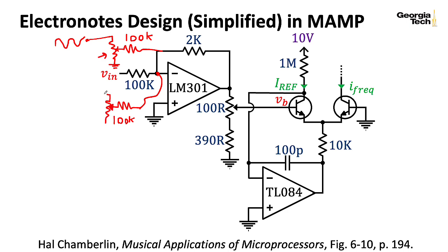You might have some sort of resistor here and some sort of resistor here going to whatever your positive voltage supply is. Let's call it VCC just for fun. Down here you might have a VEE, something like plus 12 or minus 12 for Eurorack or plus 15, minus 15 for Buchla or MOTM. This would basically set a base pitch before you put any input into it. So even if you didn't plug in a keyboard or any other external source, you could still change the pitch by turning this knob. And this gives you a nice structure for mixing all of these control voltages together.